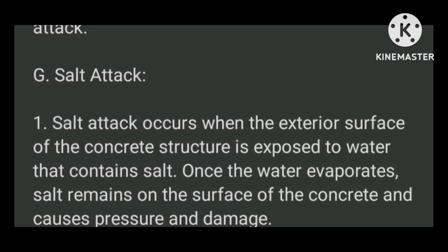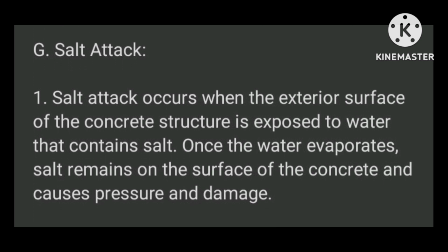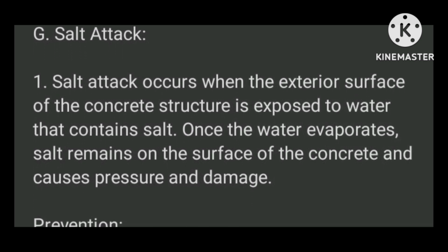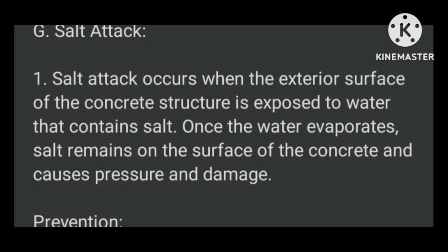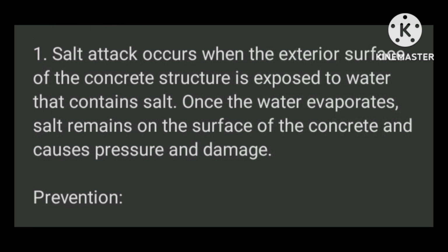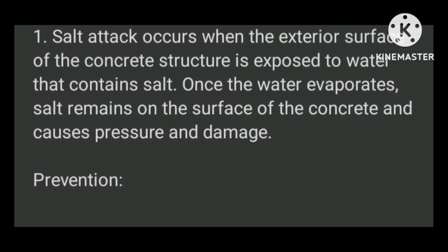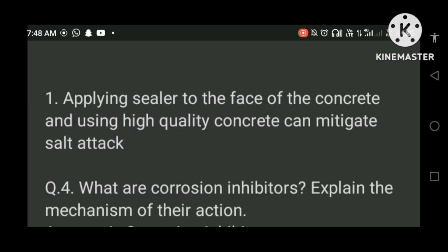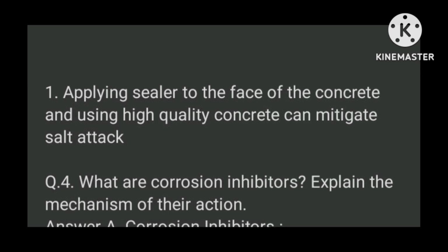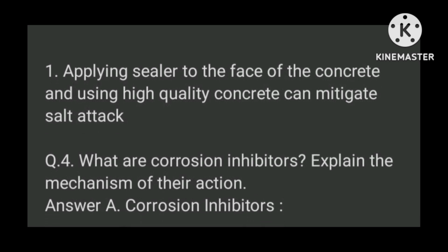Salt attack. Salt attack occurs when the exterior surface of the concrete structure is exposed to water that contains salt. Once the water evaporates, salt remains on the surface of the concrete and causes pressure and damage. Prevention. First, applying sealer to the face of the concrete and using high-quality concrete can mitigate salt attack.